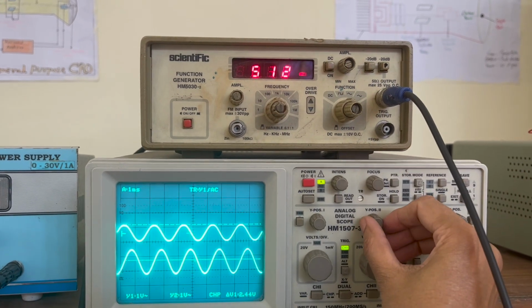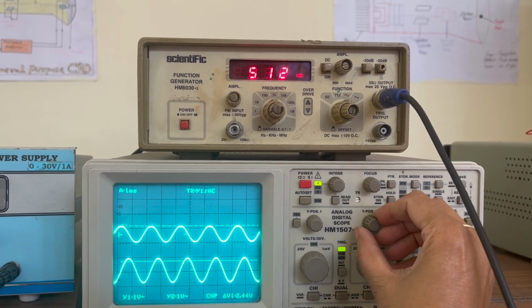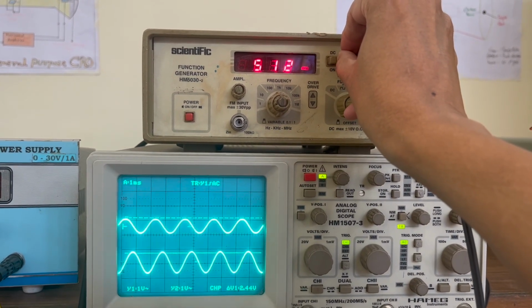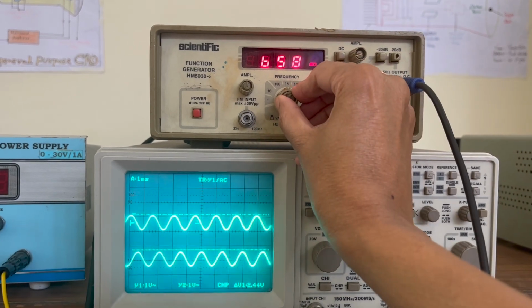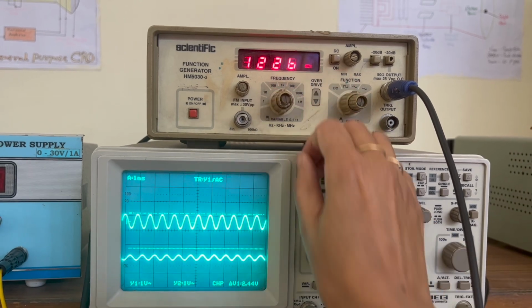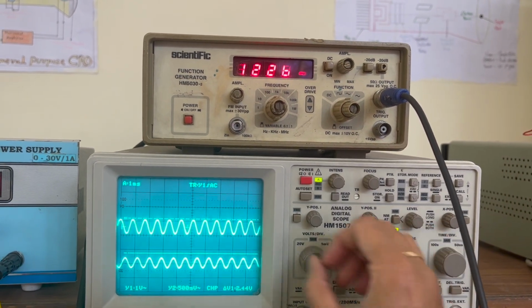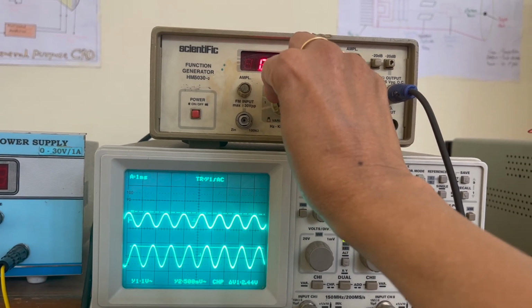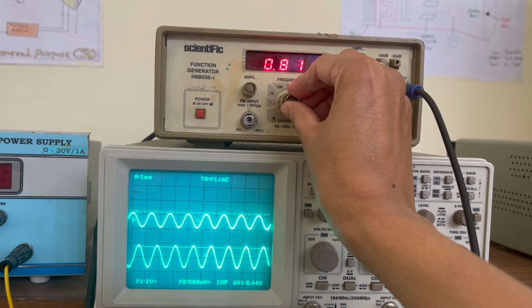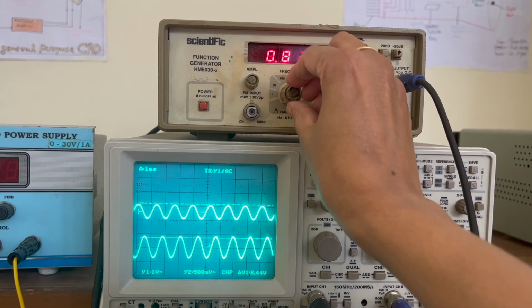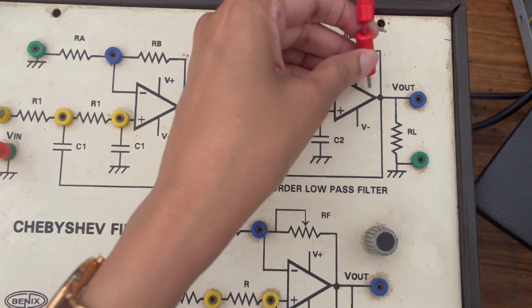300, 500 hertz, up to 500 hertz. I am changing the position of the output waveform. The lower one is the output waveform as before. The input amplitude I am reducing to 1 volt, and we are observing the output. So, at 1.2 kilohertz the output amplitude becomes smaller, right. And as we go to 0.8 kilohertz, the output amplitude is bigger. So, it is a low pass filter. You increase the frequency, the output becomes smaller.